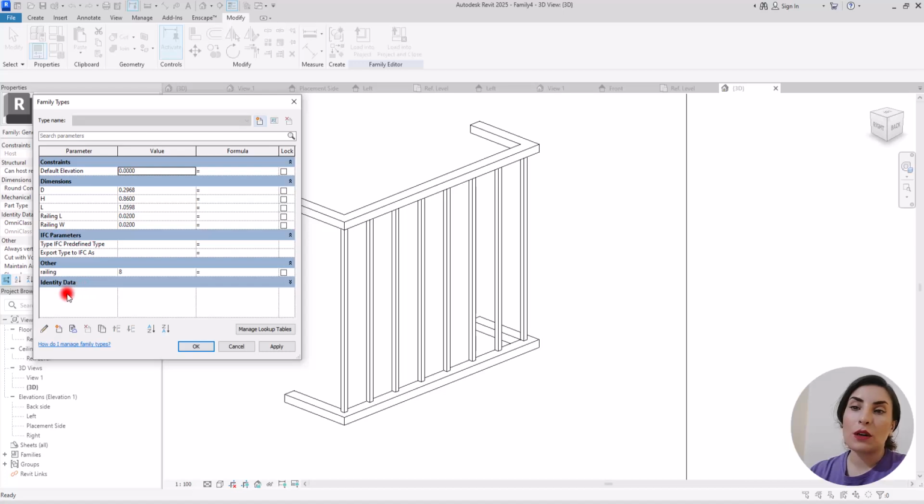This railing, we want this railing to work according to the lengths, right? So we need to connect these two together. For example, let's say we have a 1 meter length in here, and we want the distance of the railing to be like 10 centimeter. In front of railing, you need to write length divided into 10 centimeter.